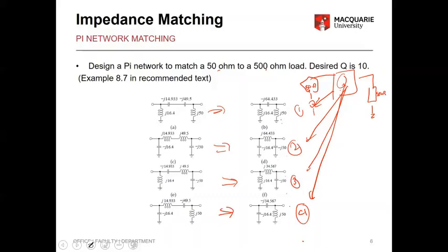For a high pass, you need a capacitor. So you might pick one of these two based on that. And also you might need a DC block in the input stage and not short the supply. So you might use that. Depending on your requirement, you might choose which impedance matching network you need to use. We won't have to go through each example in detail because of the limited time.